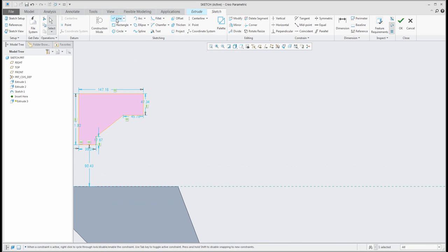The best practice is, if you create some shape and you would like to create, for example, perpendicular or parallel, equal and so on, while you see the icon, you can use the right mouse button and the system will lock these constraints for you. Then you can move the mouse and the system will always create a perpendicular constraint, for example. Or again, if I would like to use parallel, I can click the right mouse button and the system will lock this information for me. And if you would like to use coincident, no problem, click the right mouse button.